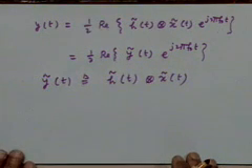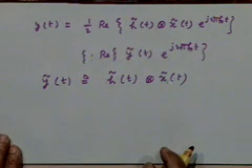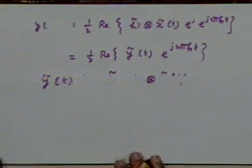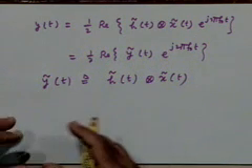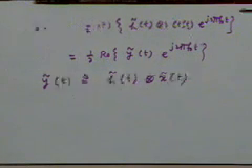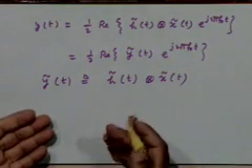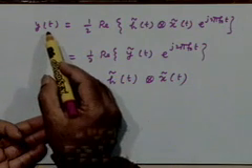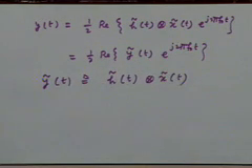And this is a result which has a lesson for us, the most important lesson which I want to talk about in this discussion. We could have avoided all these lengthy integrations that we have just gone through if we had recognized this fact, and this is what I was trying to say in the beginning. I don't have to carry out a convolution of a bandpass signal with the bandpass impulse response.